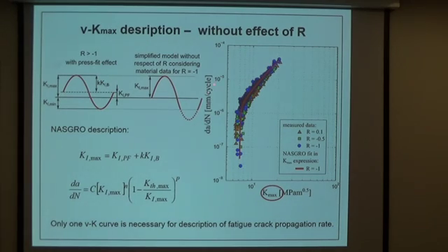So if we take into account just the data for stress ratio -1, we also assume some imaginary part of a cycle which is not in reality. So then, if we take just K max instead of delta K effective, we will obtain quite a similar trend as in the previous case.